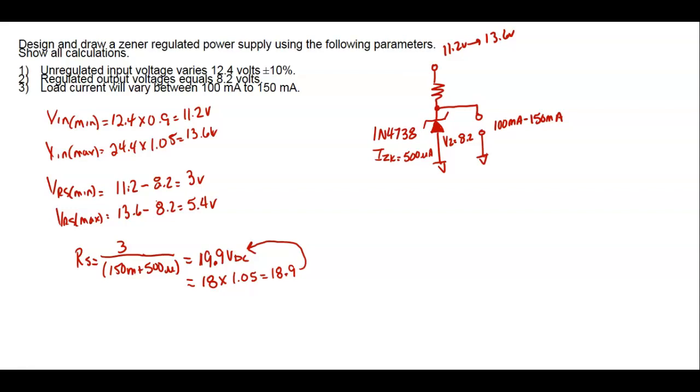So now I've chosen a resistor. Now I've got an 18 ohm resistor, so you don't use that anymore. We're through. Once we choose that resistor, that's the resistor we're going to use from now on. Right? Understand? Yeah, that's the problem we have, right? Because we came up with a 19.9, but there's no such thing as a 19.9. And if I used a 20, it would have definitely gone out of regulation, right? You understand that? Are we okay? Does that make sense?